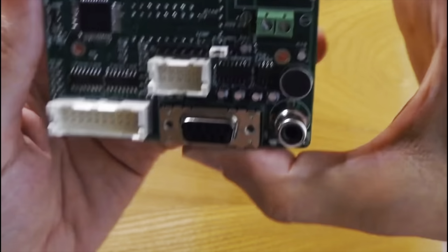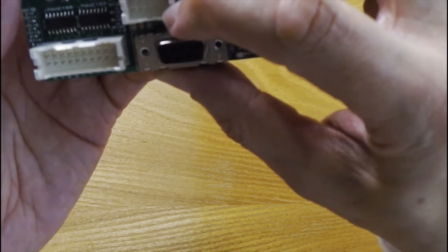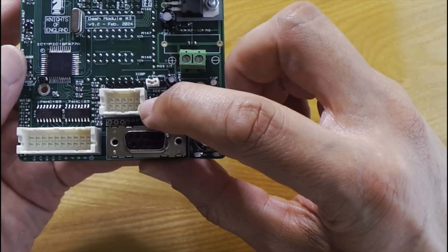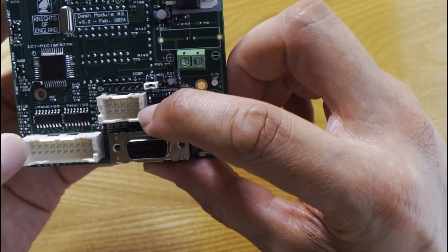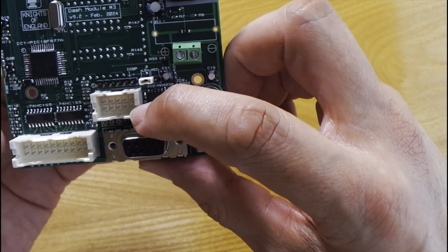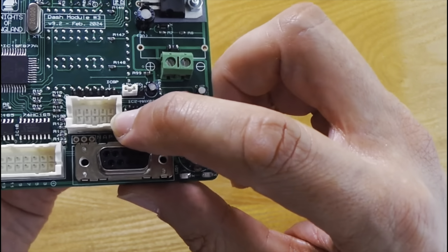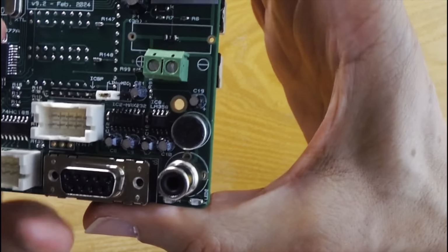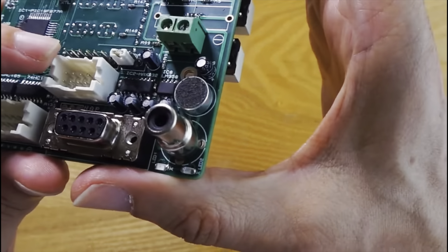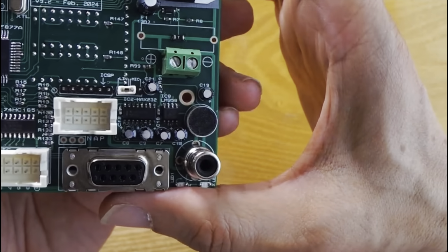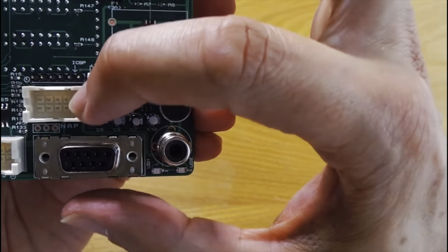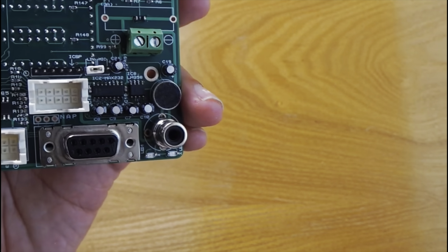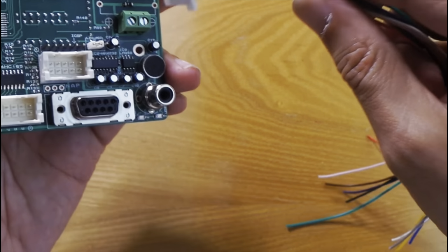We have two what are called JST type connectors on the unit. One is a 10-way connector here, and one is a 20-way connector here. The 10-way connector is going to be common, i.e. the same on all version 9 dash modules, and it has a pinout which will be the same across all modules. So let's go through the pinout for this unit, because this is the one that you'll really need to connect. Now, here is the plug which mates into that,